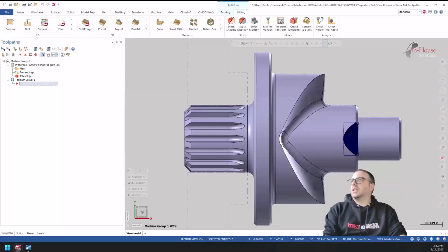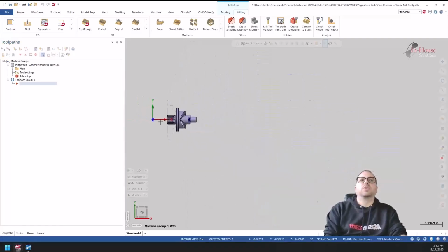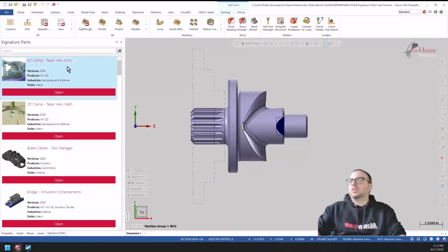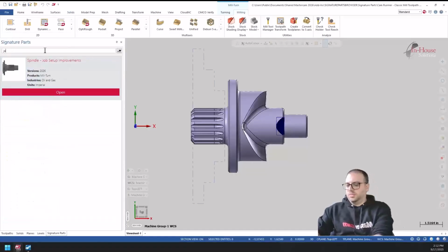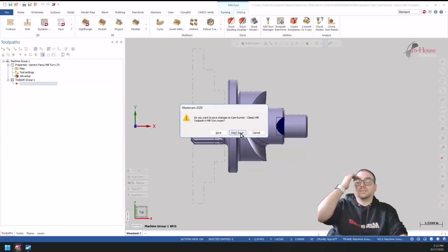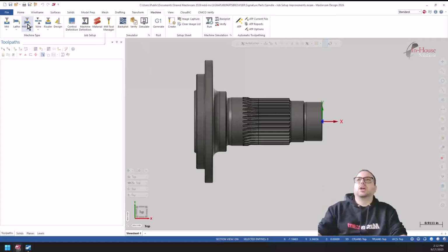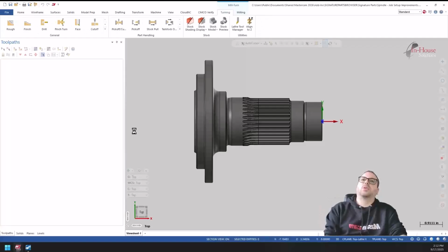So I did that job setup improvement. In your job setup, let me just use a different file here. It's related to plane grouping. Within your job setup for Mill-Turn, you now have an option you can activate to make sure all the planes that are created with Mastercam Mill-Turn are created with their own group.